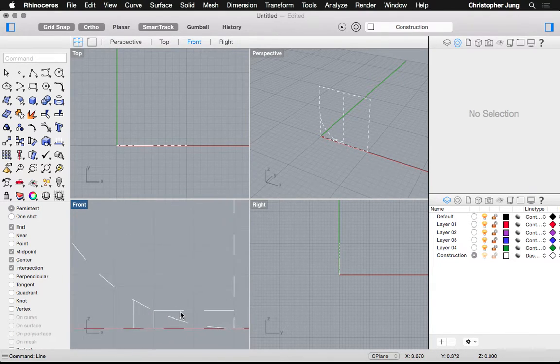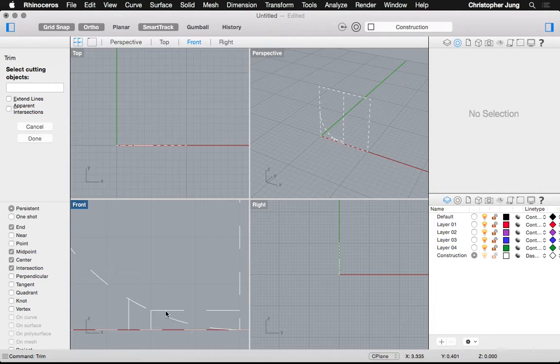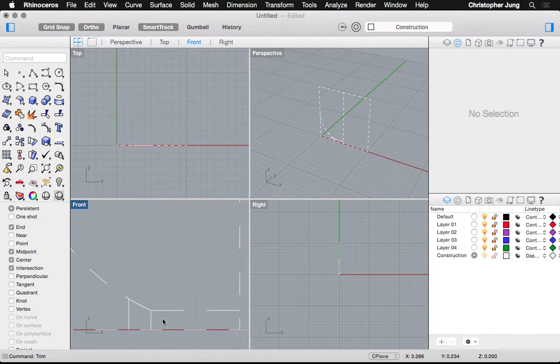And then I want to take this bottom off. Trim. So now we basically have an outer shell of a cup right there. Now, if you're making a one-part mold, all you would really need is that outer shell. But we're going to make like the whole cup, meaning the inside as well, in case you want to make like a two-part mold.